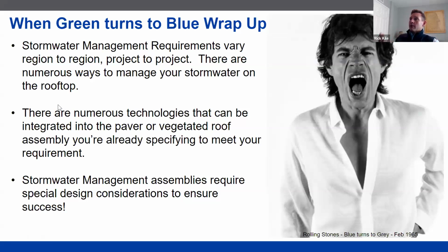I think if you're already going to have a vegetated roof on it, either because it's part of the design criteria of the project or it's municipality mandated, I would always reach out to a manufacturer, be it Siplast or somebody else, and have them run the stormwater management calcs for the green roof at a minimum, because you can start to offset some of the sizing of your detention tanks or other methods. So you might as well get credit for it, but it's got to be identified early.